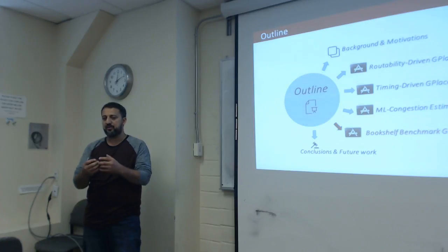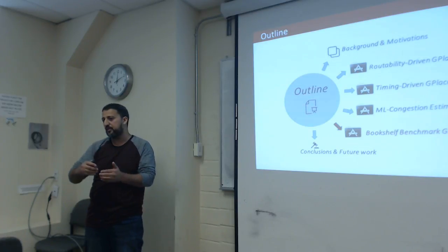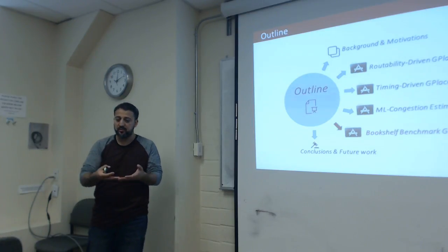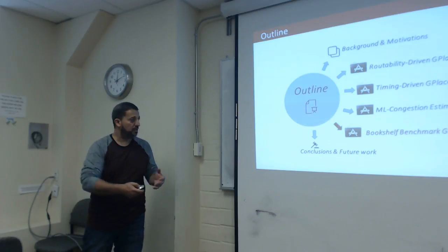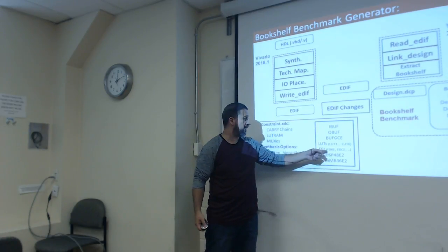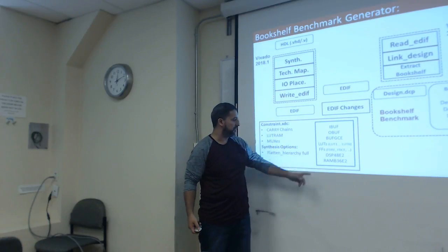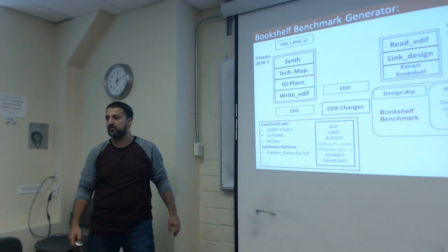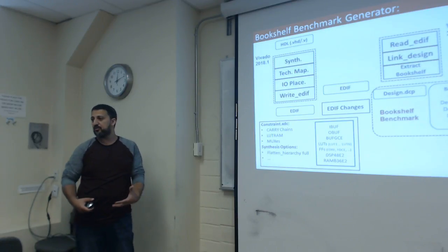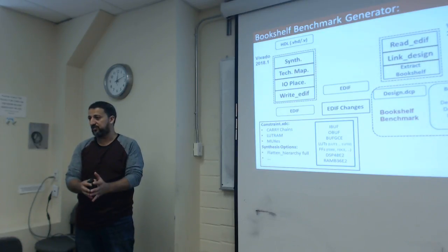So we take the HDL or high-level synthesis, but we try to generate a circuit that keeps the same functionality. We don't want to change the functionality of the circuit, but we need to have only bookshelf-like components, the only components that we handle. We can handle different flip-flop types, different LUTs, and buffers, but no carry chains, no muxes, and some other things. So it's challenging to keep the same functionality while having only those components.